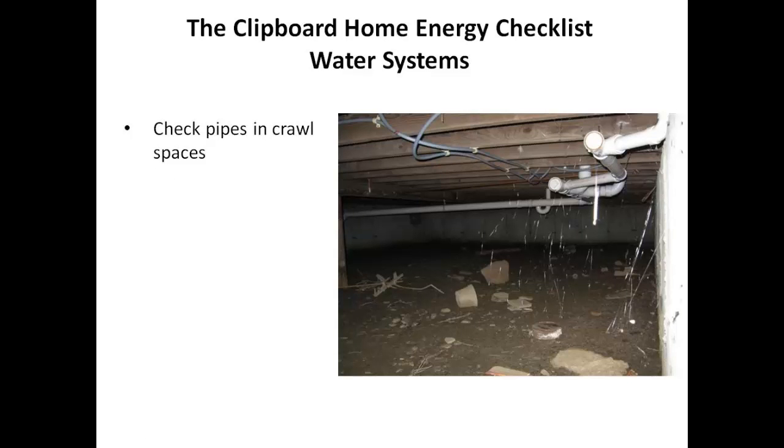There was a question about why that freezing would have happened even sooner, and that is because if they would have insulated the floor joist where the room up above is a conditioned area that gets heat, then the heat would not have been able to travel down into the crawl space, and that heat probably helped keep that pipe from freezing for some time until the temperature got so low that it couldn't. If they would have had that floor insulated, then it would have been colder down there sooner, and the pipe would have been frozen and broken sooner. So the lesson there is, make sure your pipes are well protected by being up against the floor with the insulation on the outside or the cold side, so that that pipe stays warm.